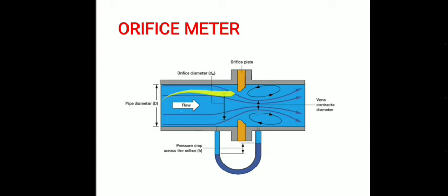After passing through this orifice the area of this flow is reduced to a minimal dimension, and that point having a smaller area of cross section as compared to the previous area is known as vena contracta. We will discuss this term vena contracta in the following sessions.